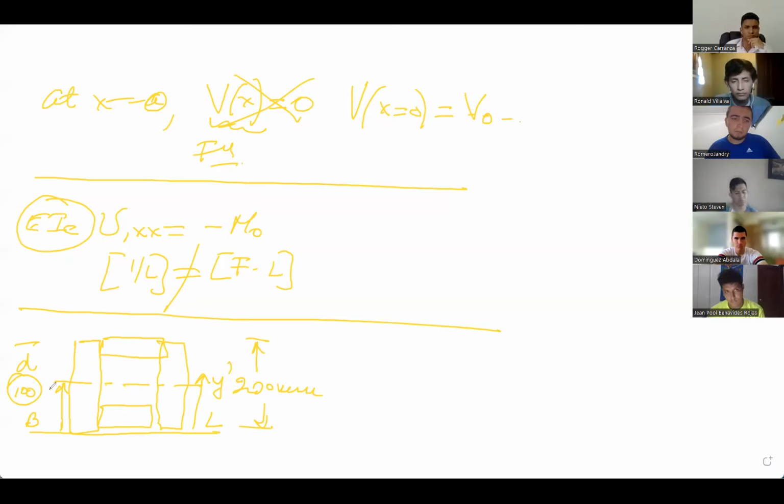The problem is that, please review your work. Review your work, and see how many of you calculated something different than 100 and said nothing. So you said, I calculated, I don't know, 70 something millimeters, and you went on with the calculation. That means that you're not thinking. This is a symmetric section. If you obtain a value which is different than 100, you shouldn't go on. You should go back and check what is the error.